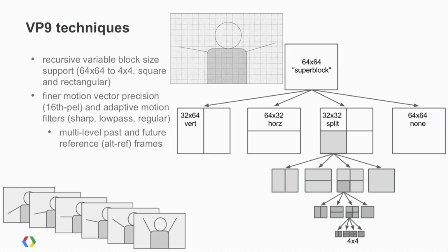And then, now that I've encoded 3, I can encode 1 and 2 really efficiently because they have a very proximate future and past reference. After I've encoded 2 and 3, I go to 5, which has 4 and 6 as close neighbors. And so that allows for very temporally close reference frames to be used as a predictor of contents in the current block.